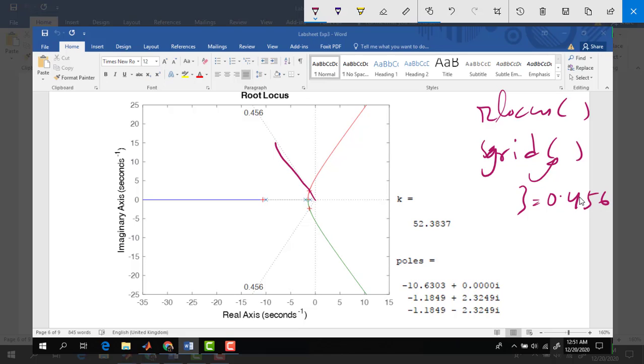The first one is the red line of the root locus, and the other one is the dashed line of the sgrid. So we will choose this point. Whenever we choose this point, the rlocfind command will give back the K, or the gain, and the poles associated with it. You can see we get 3 poles. 2 will be here, and another one will be in this position.